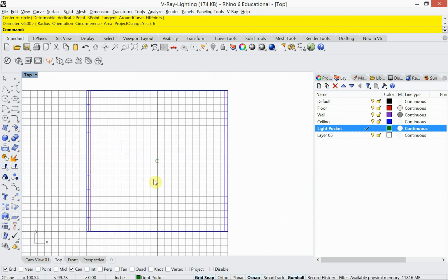Now I'm going to make a lighting pattern that you saw in that image where I just take this and I copy it. I'm going to use a center snap. Center's good. I'm going to take off end for a moment so I don't have to zoom in, and I'm just copying this 5 feet apart. So that one's over 5. This one is going to be over 5. I can take all of these and copy them up 5 and down 5. Okay, so that's my lighting scheme for those recessed cans.